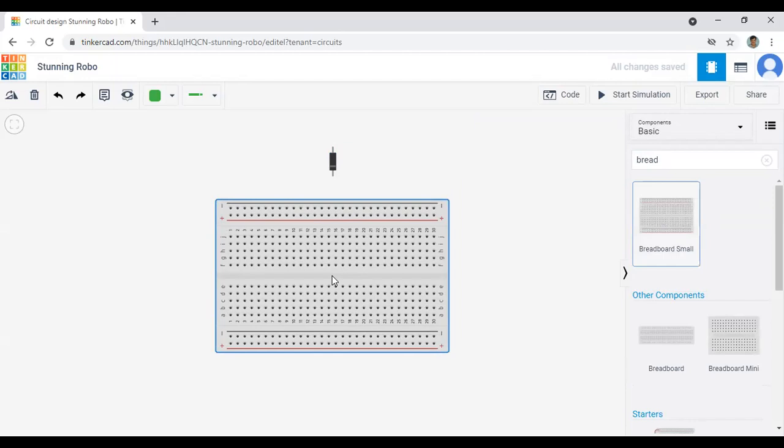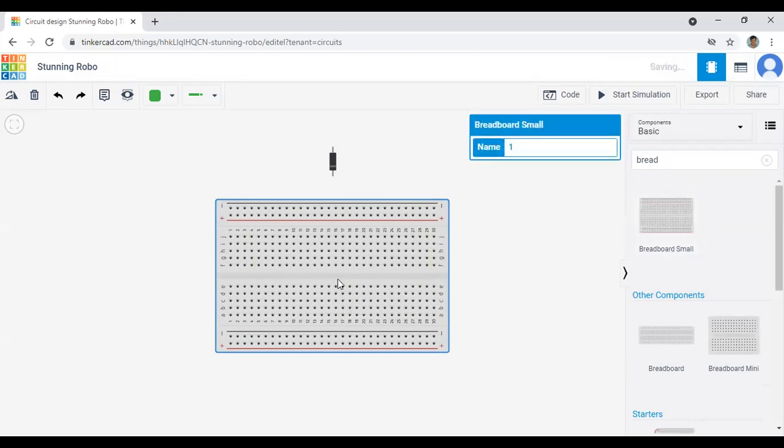This breadboard we use for making connections. I will show that now. Look here, here you can see there is a negative. This negative part has the connection running from left to right. When you connect the negative of the battery to this point, then you can place components on this side.